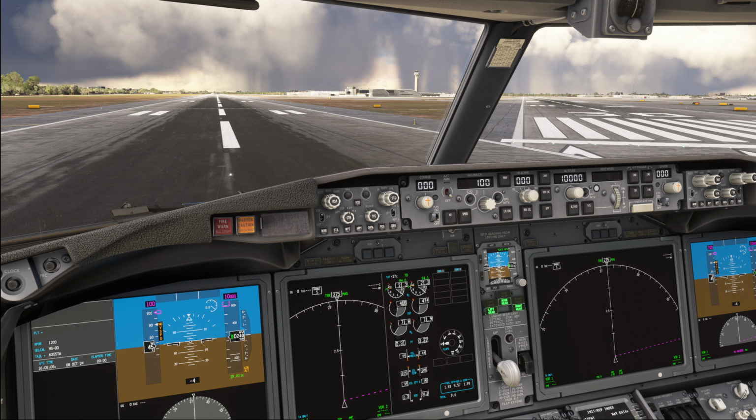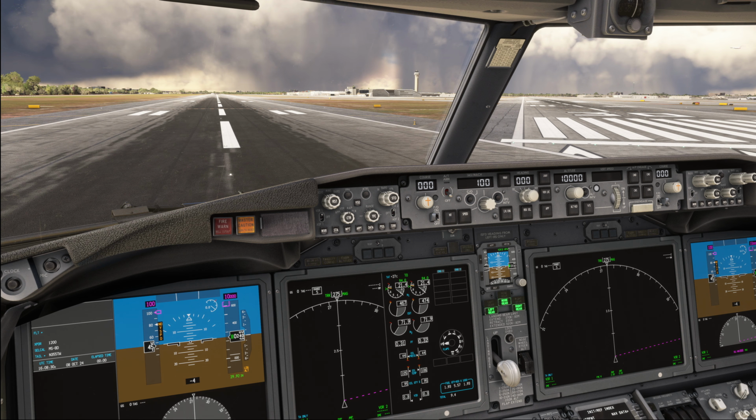In addition to ground flight and approach idle, as you have it on the 737NG, the icing idle has been introduced, and that is the highest idle setting and is selected by the electronic engine controls in flight if the engine anti-ice is selected on and both the flaps and the gear are up. When in the icing idle mode, the EECs begin transitioning from minimum flight idle at 30,400 feet and increase idle in the descent to provide full icing idle at 22,000 feet.